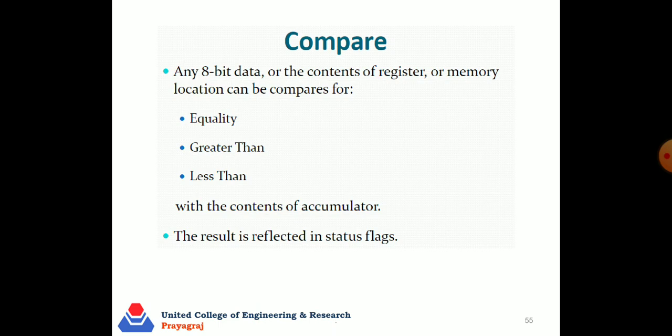Compare instruction, it's a very important instruction. Any 8-bit data or content of a register or memory location can be compared for equality, greater than or less than with the content of the accumulator. The result is reflected in the status flags.